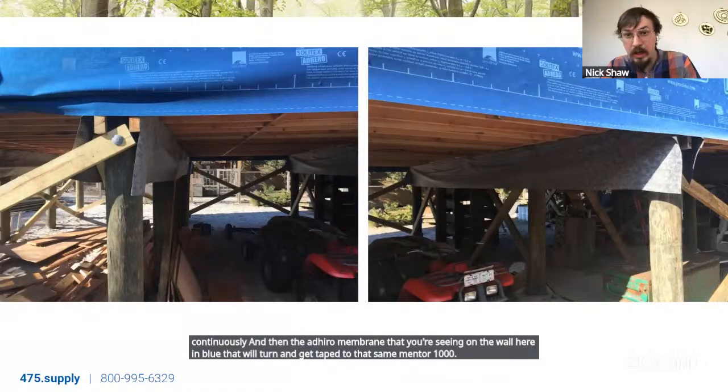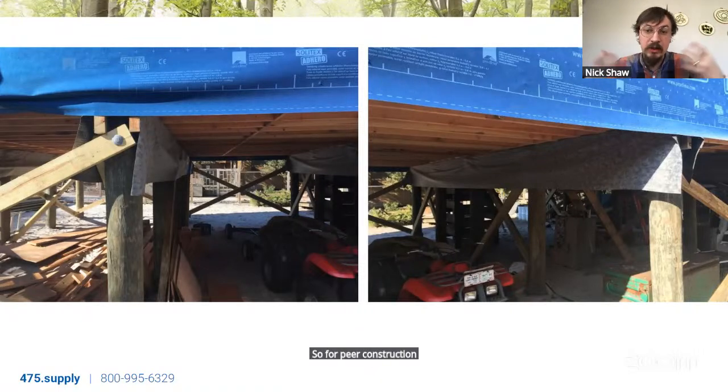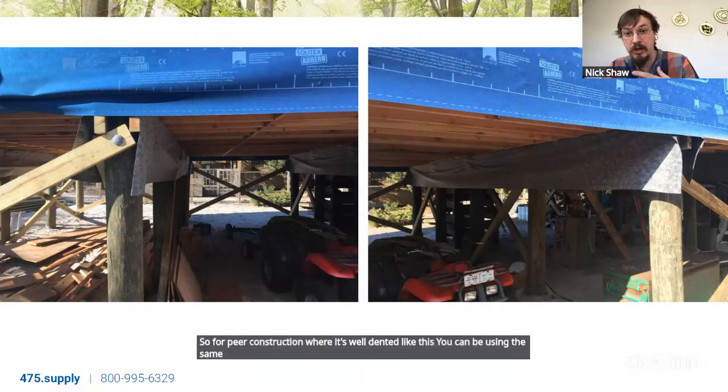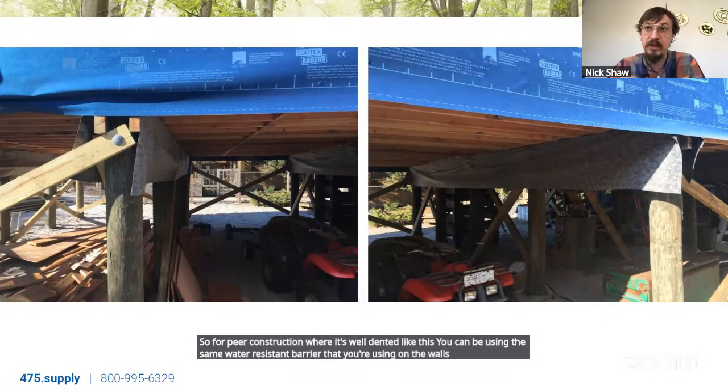So for pier construction where it's well vented like this, you can be using the same water resistant barrier that you're using on the walls for the underside of that floor system.